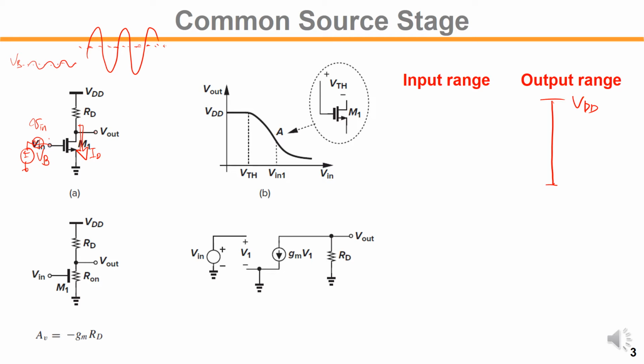If we assume the gain AV is large, so the input signal fluctuation is small, then we assume VB is around the DC level. In that case, M1 will get into the triode region when VDS is below the overdrive voltage of the input device.